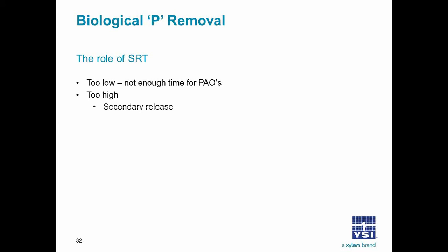As the sludge gets older, more decay occurs, and when this decay occurs, the phosphate that they had worked so hard to accumulate is released back into the tank. Competition. There are bacteria that are able to store these carbon products but without the release of phosphate, and they may outcompete the PAOs, which is also not desirable.